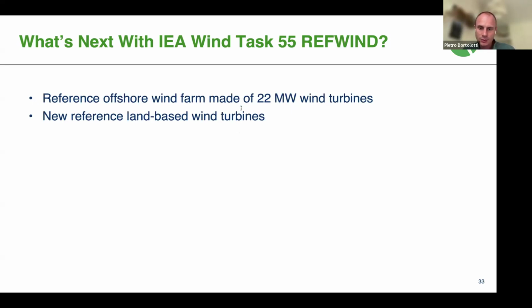There is also a question about stiff versus soft-stiff for the tower, and again, for the floater, we might need to rethink the tower a little bit. But we did not think that it was realistic to design a stiff tower at this scale. The tower masses were simply, well, I would say outrageous. So right now, it's a soft-stiff design.